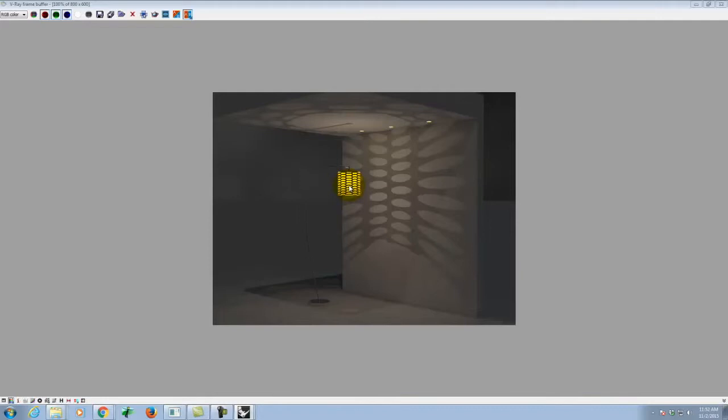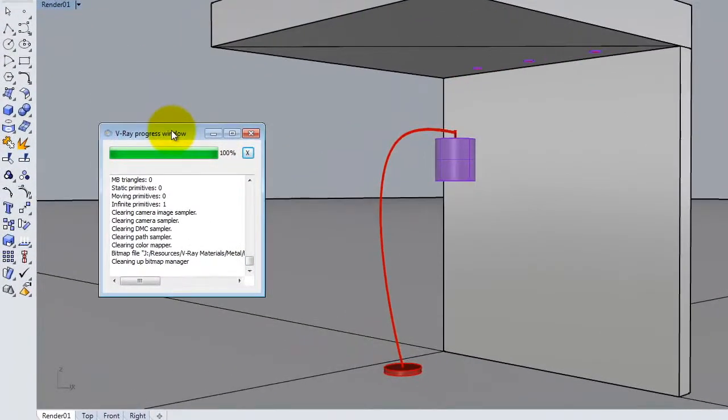So today, for exercise 222, I want you to play with a point light and a spotlight. Those are the two primary lights that we're going to work with. There are other types of lights that are available in Rhino. They're much harder to give you a script for, saying these are the settings. A rectangular light, for example, is a great kind of light, and I'll use it a little bit later on, and show you a place where it'll work. But it involves a lot more experimentation to get the settings right. With a spotlight, if you generally follow these rules, you'll generally get a good quality spotlight. A point light, if you generally follow these rules, you'll generally get a good point light. That's why we start with those two and get you comfortable with lights and lighting.